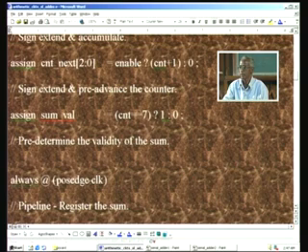Only when that 7 is encountered is this 1 assigned to the sum valid, otherwise it is going to be 0. For all the other clocks, right from the first to the 7th clock, naturally the 0 will be forced to this one, and only with the arrival of the count value 7 will it be made 1.